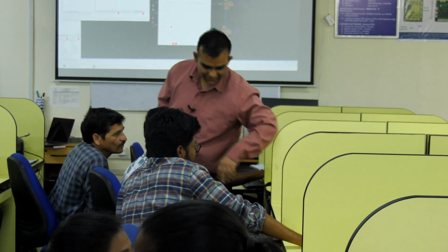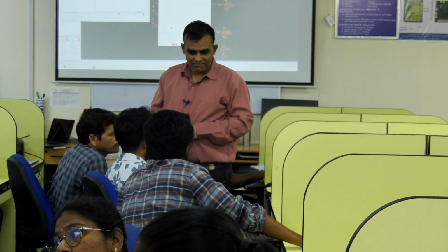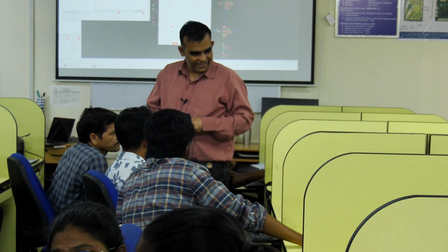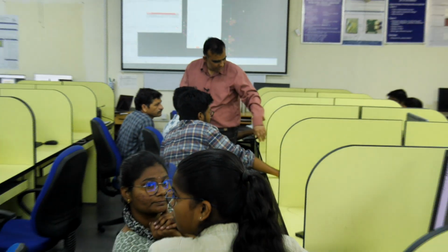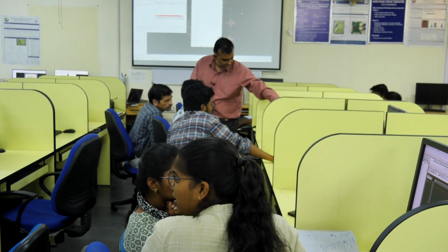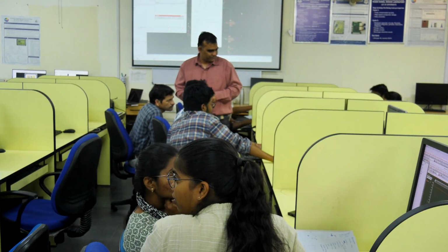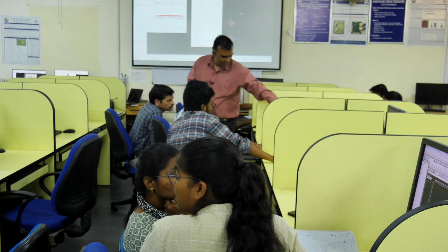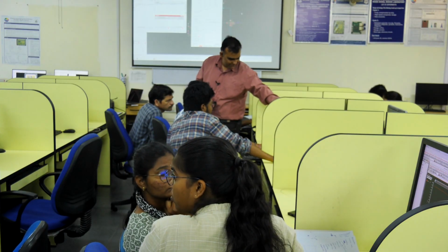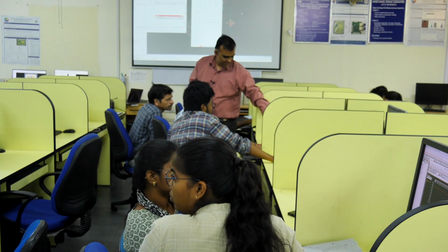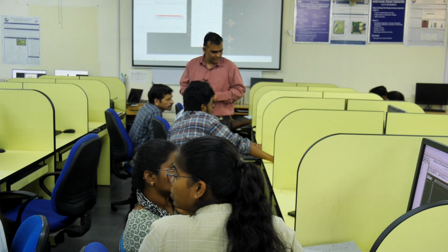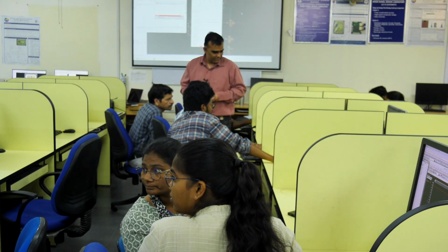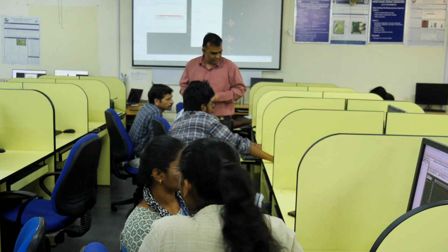Yes. So other than connecting everything, let's do a DRC check. Can this be manufactured? So go to Assura and do run DRC. Just click OK. Everything should be set. If it's not set, we will know anyway.